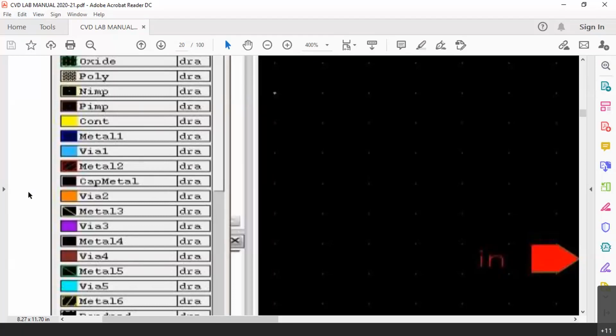In the nanometer dimensions, even though the wafer is hardly 0.4 mm or 0.6 mm in size, the silicon wafer is less than 1 mm in thickness. Now in that less than 1 mm thickness, we are having multiple layers. All these layers are not even in millimeter dimension. They are in micrometer dimension. Transistors are in nanometer dimension. So the chip should have enough physical strength to handle all those layers.